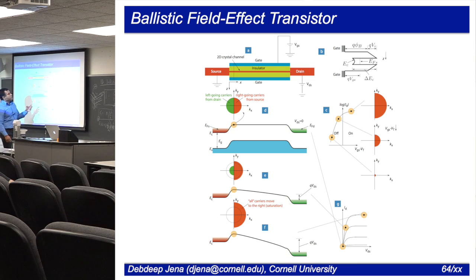Similarly, when the gate starts saying that I go to very low carrier densities, all the carriers are going to the right, but then you go through a log scale behavior, meaning the carrier density goes down exponentially, and you're kind of shrinking the right-going state. The area is now shrinking when you change the gate voltage and we want to remove the electrons. All these are the same electron density, meaning these curves are explaining why it's 0 initially because they're the same, why it goes here, because all of them are moving to the right now.